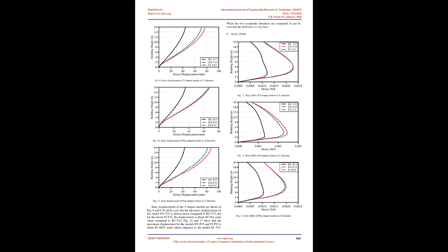Helps in avoiding the steel beam and concrete slab splitting at the interface/junction. The overall depth of the beam is decreased by the action between steel beam and concrete slab. A metal deck sheeting is provided on the beam, and with the help of shear connectors the deck sheeting and the beam are connected. Then the concreting is done over the deck sheeting.